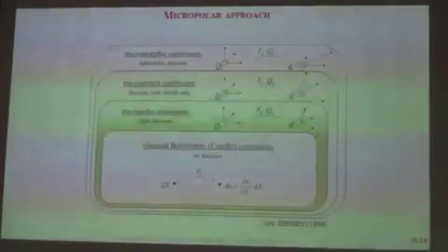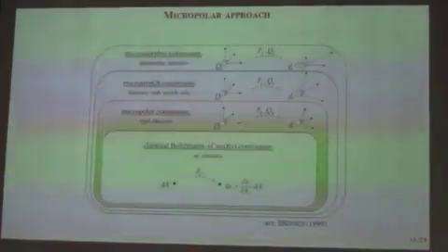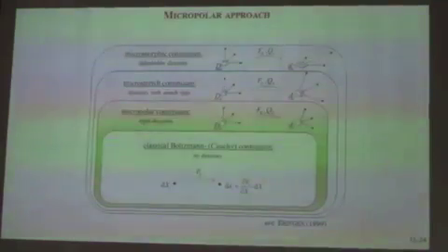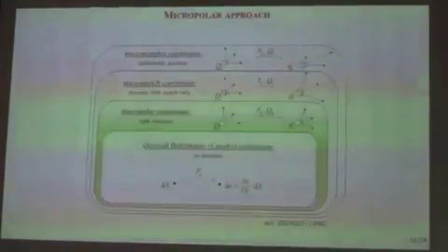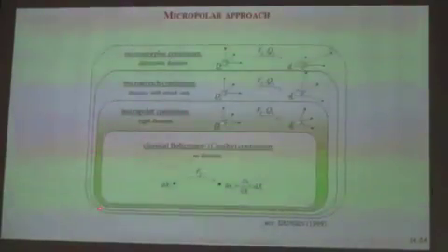If the directors are only used with stretch, we are at the micro-stretch continuum, and even if we fix the directors in their length and their angles with respect to each other, then we are at the micropolar continuum, where we have rigid directors, and due to this also a rigid particle that is just supposed to be able to rotate. And of course, in the classical Cauchy-Boltzmann continuum there are no directors and no higher gradients.